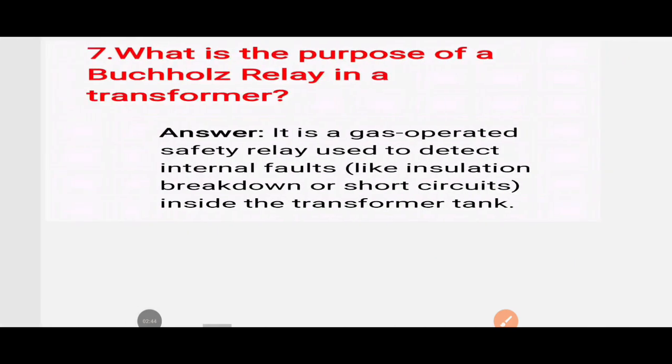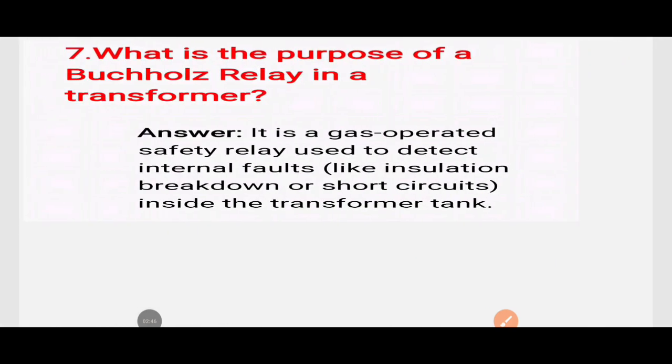Next, what is the purpose of a Buchholz relay in a transformer? In a transformer, Buchholz relay is a gas operated safety relay which is used to detect internal faults. Internal fault means things like insulation breakdown or short circuit inside the transformer tank.